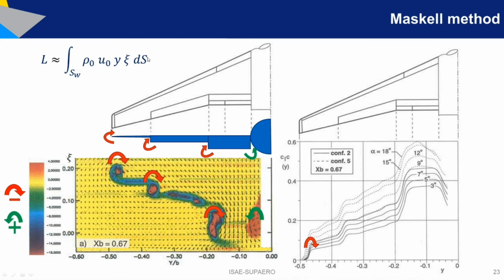It really allows you to understand the implications of the vorticity, and you know vorticity is generated by the surface, so you can actually link the geometrical parameters with the vorticity generated, with the lift it generates, and also with drag, because don't forget that vortex drag can be computed only from actual vorticity. So the key parameter here is actual vorticity, and it's linked with the geometry.